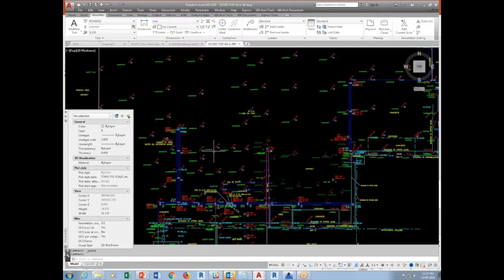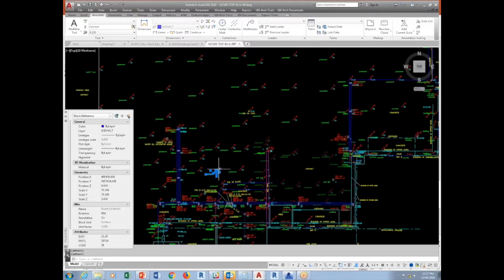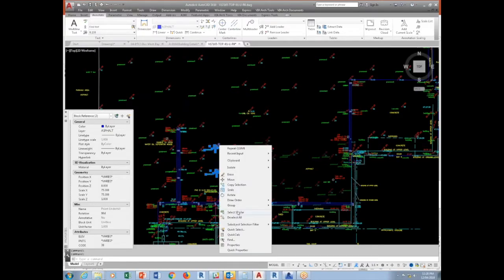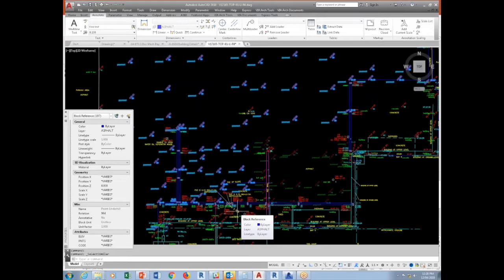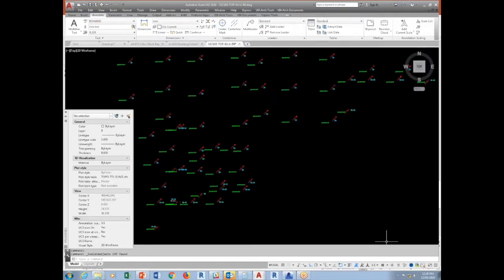Okay, if you want to select certain objects inside AutoCAD, let's say for example this one, rather than picking individually, you can right click and say select similar. And what it does is that it will basically select those objects together. Now, it has this called isolate objects. You can hide objects or isolate objects, similar to how Revit does it, right? So you can hide certain objects. Use this a lot, okay?